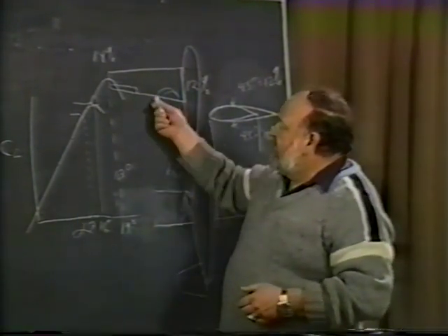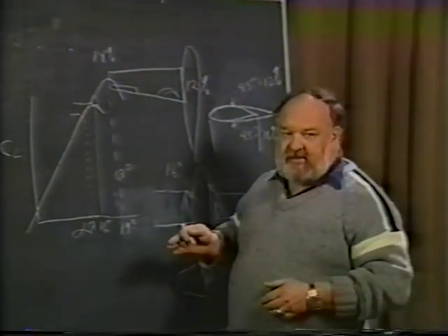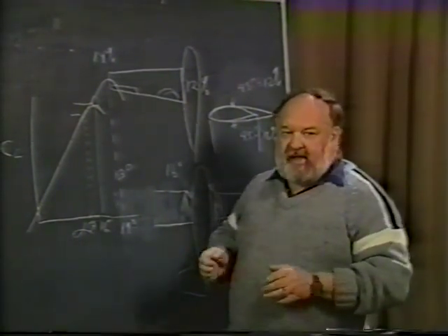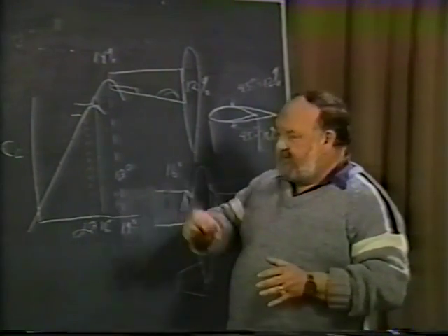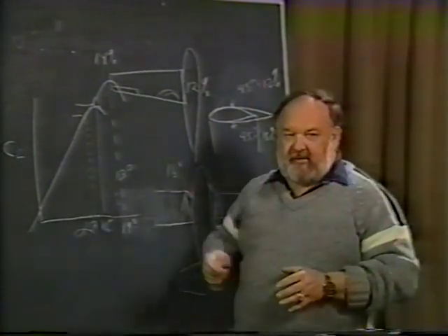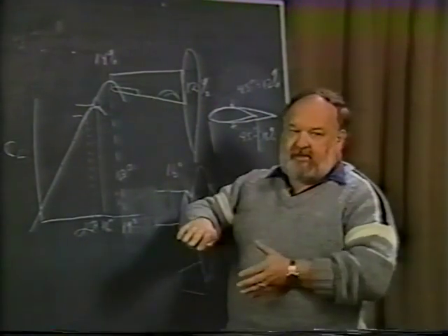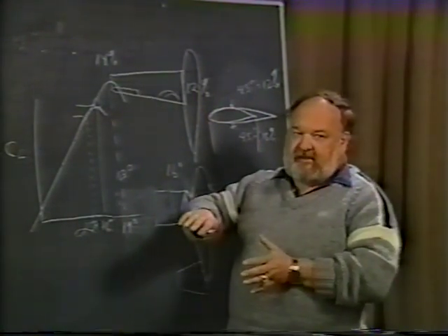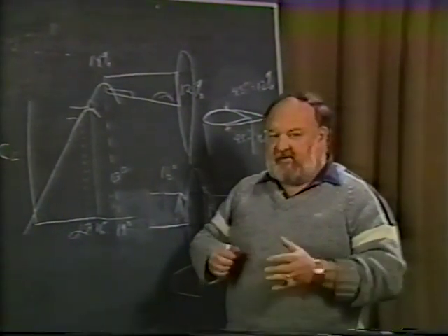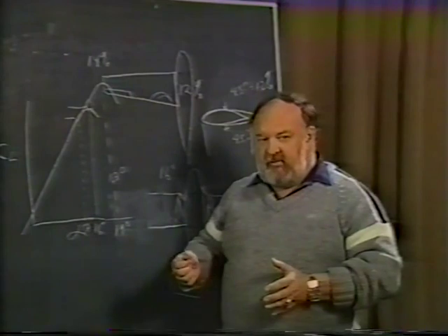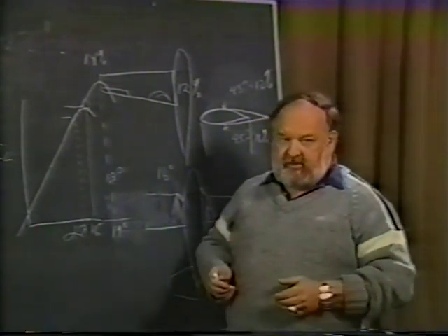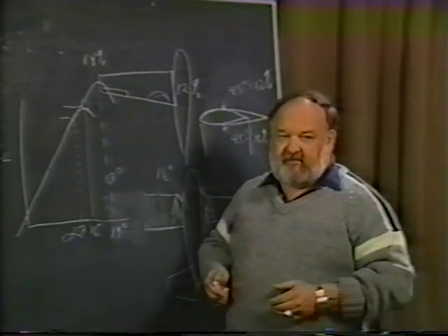In the case of this design, we could actually sit there, be buffeting, getting this inboard section to be separating, and as we're doing that, be able to sit there and move the ailerons right and left, no problem. I'll get beautiful roll control out of it. So this meant that as you were turning from base to final, if you accidentally let the airplane get too close to stall and start getting a little buffeting and realized you had a problem and forgot good judgment and went ahead and moved the ailerons as opposed to getting out of the near stall condition, you didn't do a major mistake. The airplane itself could recover.